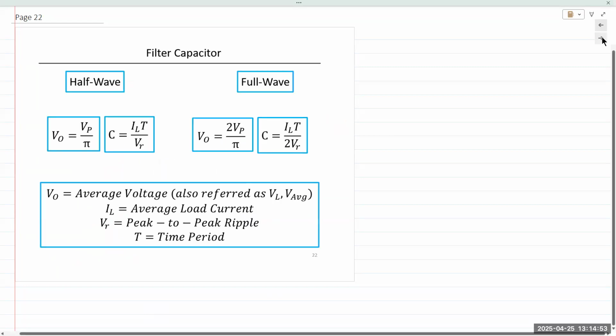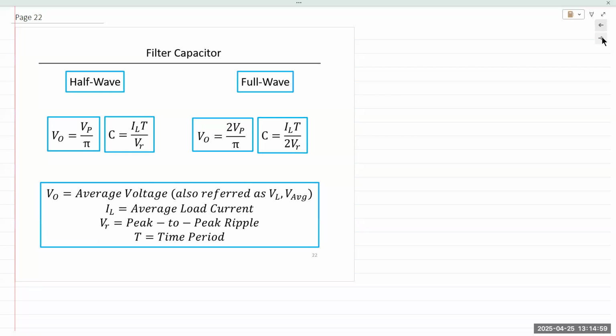All right. So, filter capacitors. The purpose of the capacitor is to eliminate the ripple. Depending on our requirements, we would want the ripple to be almost non-existent or at least very, very small, right? No circuit is ideal, no capacitor is ideal. So depending on the size of the capacitor, it's going to affect circuit operation.